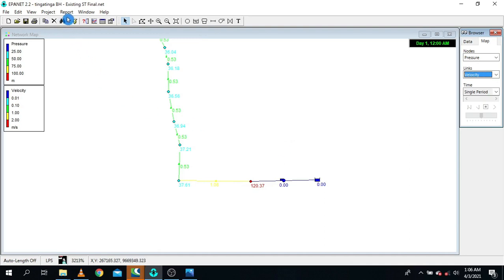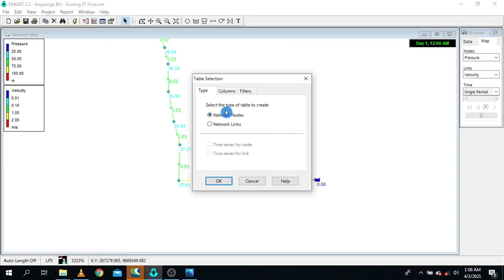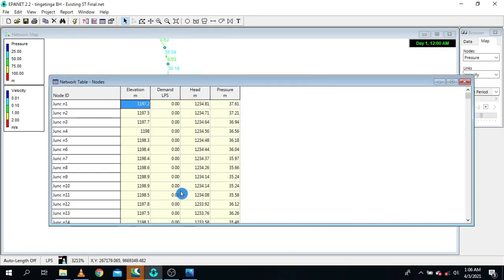So that being said, this is the final part, but not over yet. We need also to see how we can extract our reports. There are 2 ways that you can extract reports from your project. The first step is to go to this table here and click. Let's start with nodes. From nodes, we don't want to see quality, but we want to see elevation. Then click OK. So this is the data. At every node you have your pressure values here. You can just click them and see. So this is a pump, if I'm not mistaken. As you can see here it is 120.